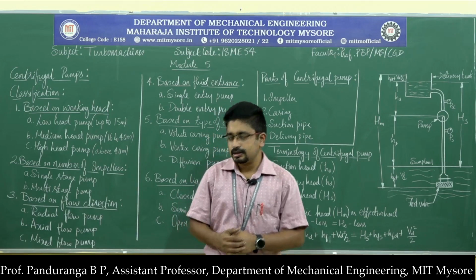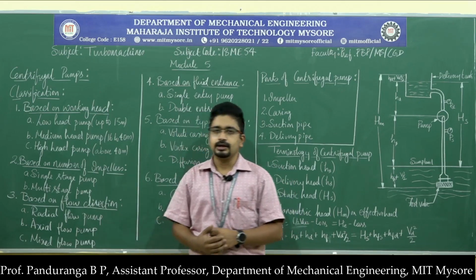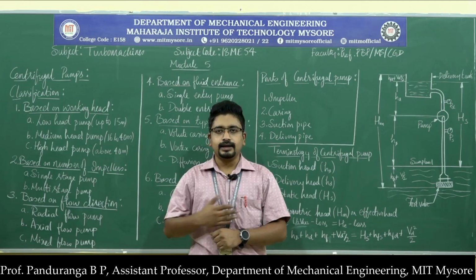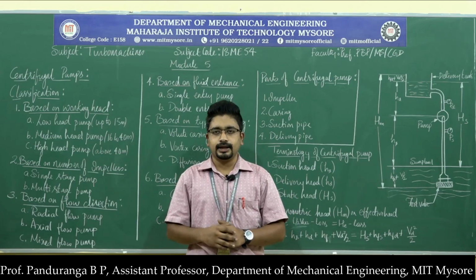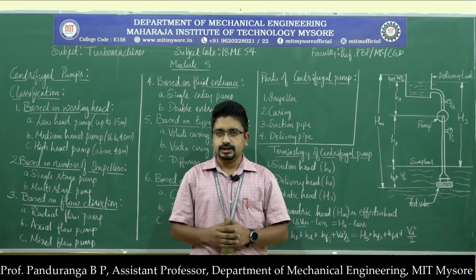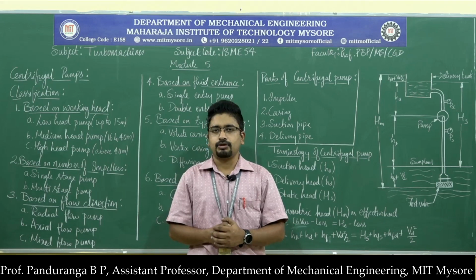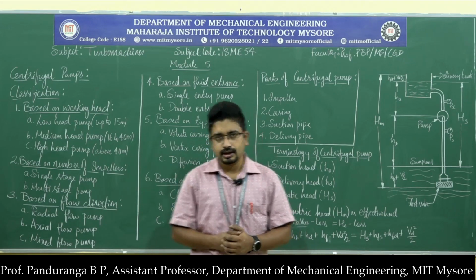So those are the mixed flow pumps, where the fluid enters parallel to the shaft, or in the axial direction, and leaves the pump in the radial direction. So these are used where you have medium head and medium amount of discharge needed.